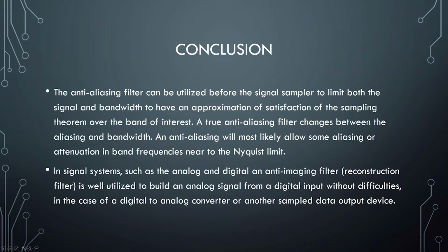So in this case, we were using some principles of signal sampling and reconstruction to build this electronic circuit to sample, hold, and reconstruct the signal wave. We applied the anti-aliasing and anti-imaging to perform proper simulation of signal sampling and reconstruction.